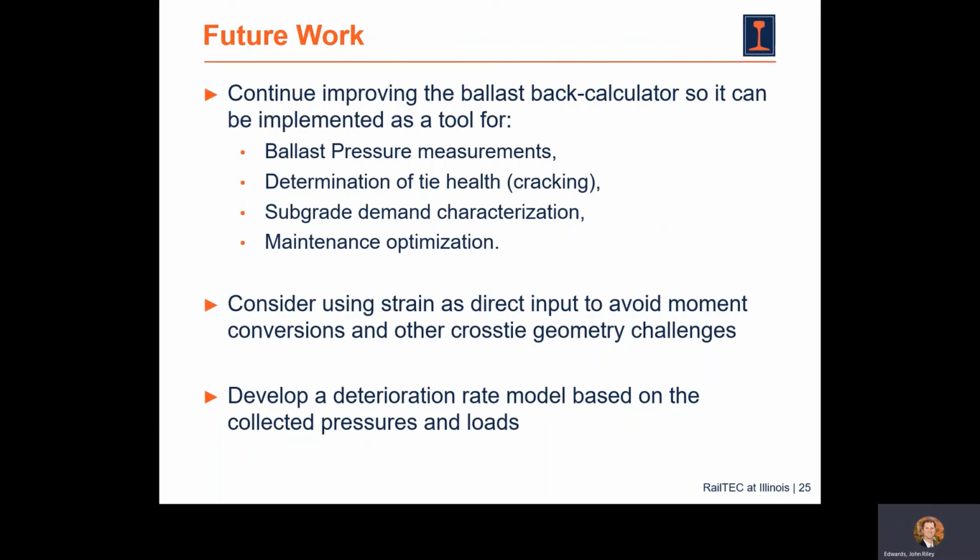Future work for this project includes further improvement of the ballast back calculator, so it can be used as a method of ballast pressure measurements, determination of tie health and prediction of cracking, subgrade demand characterization, and better optimization and prioritization of maintenance activities. We also are talking about using strain as a direct input to avoid some of the calibration challenges that you may have with moment conversions and cross-tie geometry changes with the various designs that we see out in industry today.